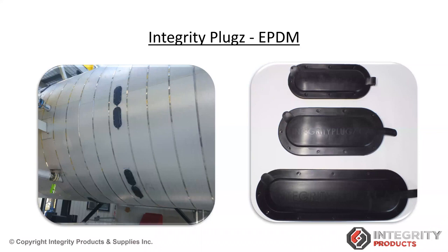We also do our inspection ports in an EPDM variant. So these come in all the same sizes, same package, everything like this. The only difference being that our silicone port has a temperature range of -150 to +450 Fahrenheit. Our EPDM variant is -58 to +300 degrees Fahrenheit. So if you've got a lower process temperature, the EPDM is certainly a good alternative as well.